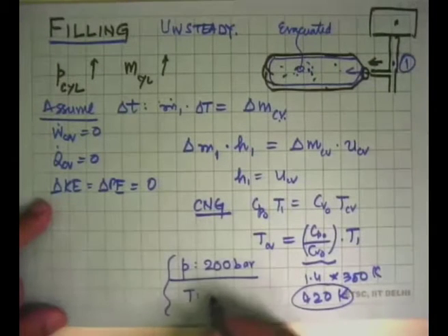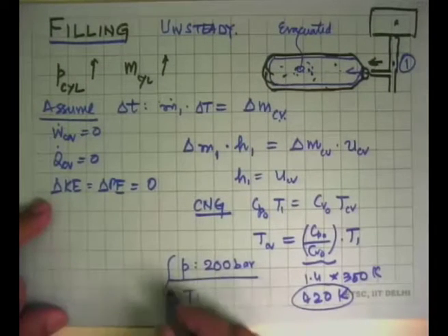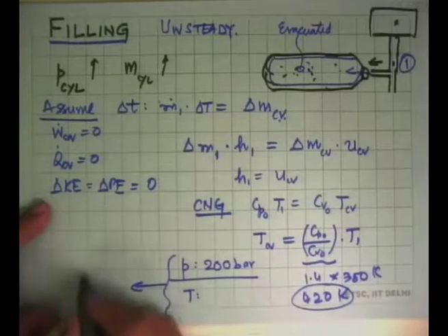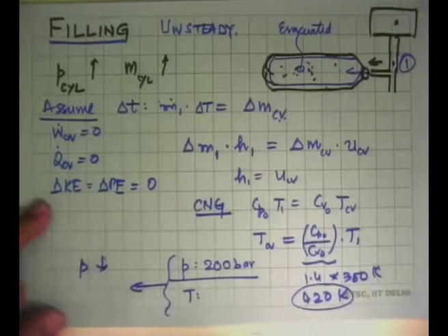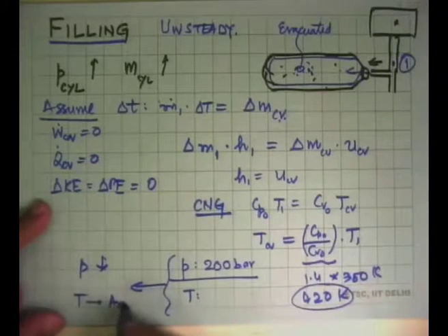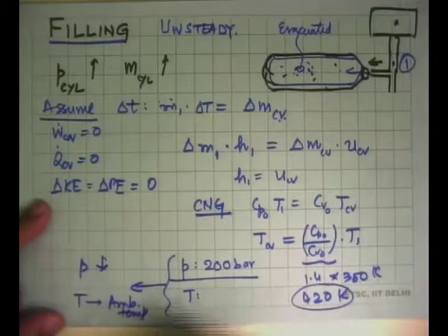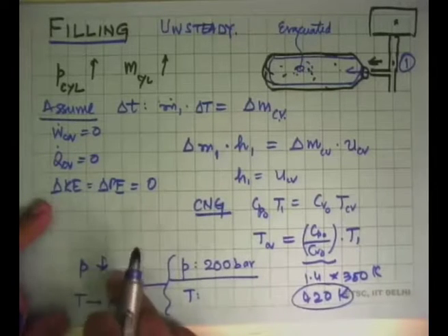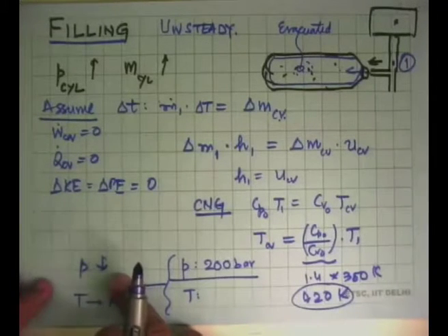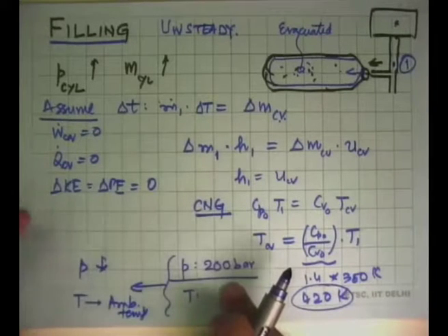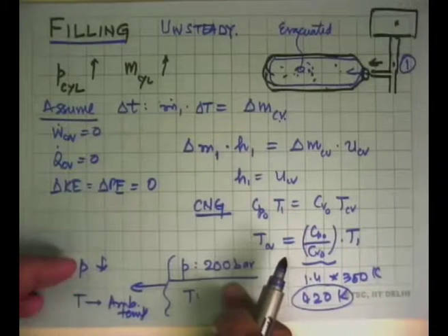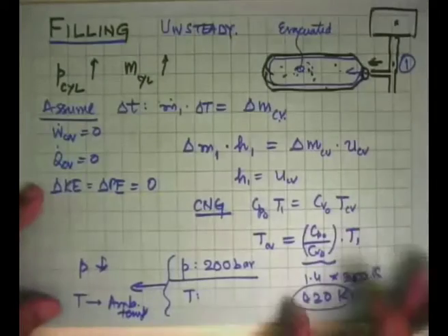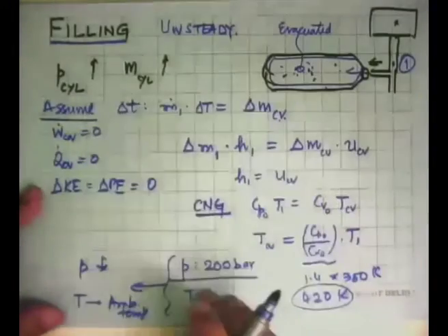Which means that if you fill it up here at a high temperature, as you go away, after some time, even if you don't use the gas too much, the pressure inside will drop as the temperature reaches the ambient temperature. So instead of say about 80, 90, 100 degrees Celsius, this will come down and the pressure will be less. But you cannot initially fill it up to more than this, hoping that after it cools down it will come to 200 bar. That is not permitted because the mechanical design of the cylinder does not permit it. So that's what happens in a filling process.